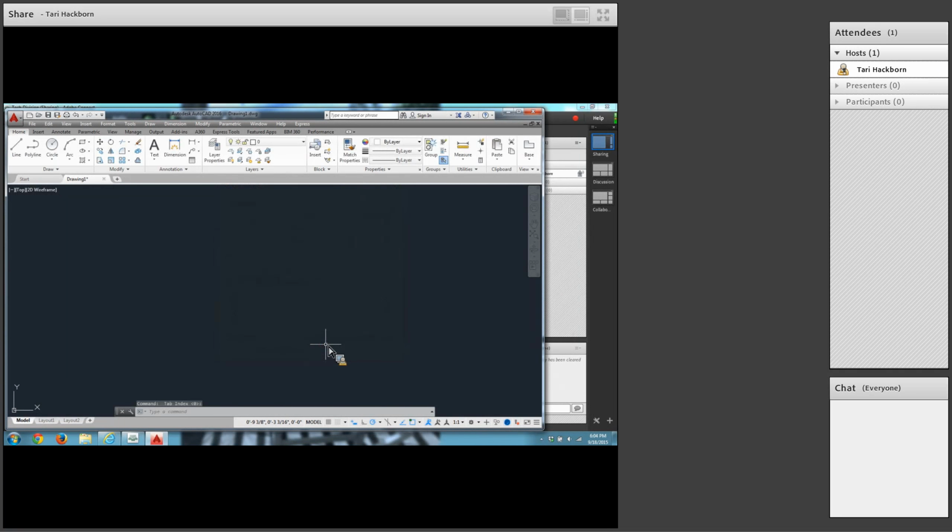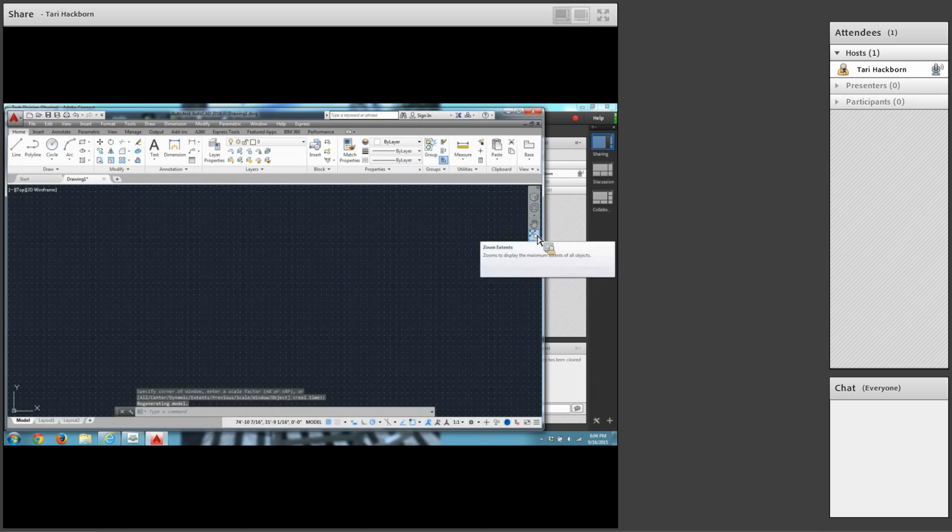Okay. And you still don't see a single dot. That's because I haven't done the extents yet. I'm looking at 12 inches by 9 inches. If I come over here and click extents, now I'm looking at my entire drawing area. Now you're ready to start the drawing. You can start this drawing anywhere, and it's not going to snap to the dots because snap is not turned on.